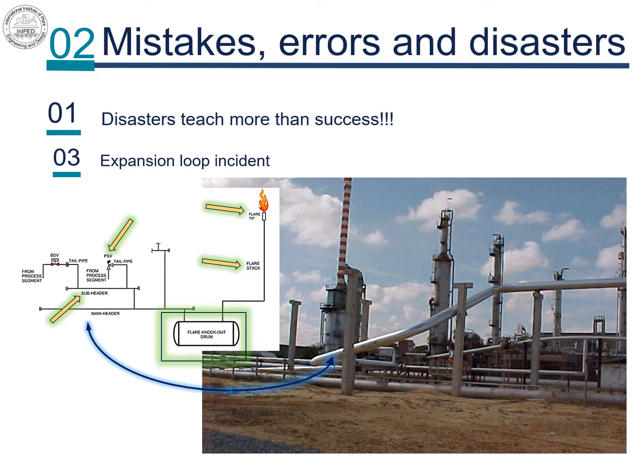Piping shall be evaluated for flexibility, and expansion loops shall be provided wherever necessary. Expansion joints shall be avoided. Flare piping loops are planned in the horizontal plane, 2D bends, in order to ensure pipe slope for free draining requirement. From this angle, it looks like that due to large thermal growth of the horizontal section before the expansion loop, pipe movement simply exceeded the available sliding space.